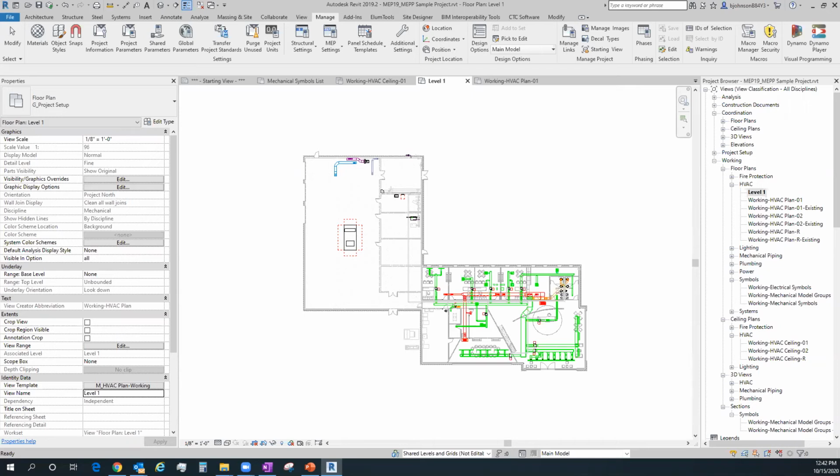There may be some other IT tracking stuff that can be looked at, but in most cases, when you do lose that little bit of information, it could be something that crashes the entire file. Maybe project setup information that Revit needs at the very start of the write of the file. Or if it's something later, it could be something built into a family, where a family gets corrupt and it doesn't know how to fully save that element correctly. So in those cases, you need to have a workflow and a methodology to figure out what actually happened.